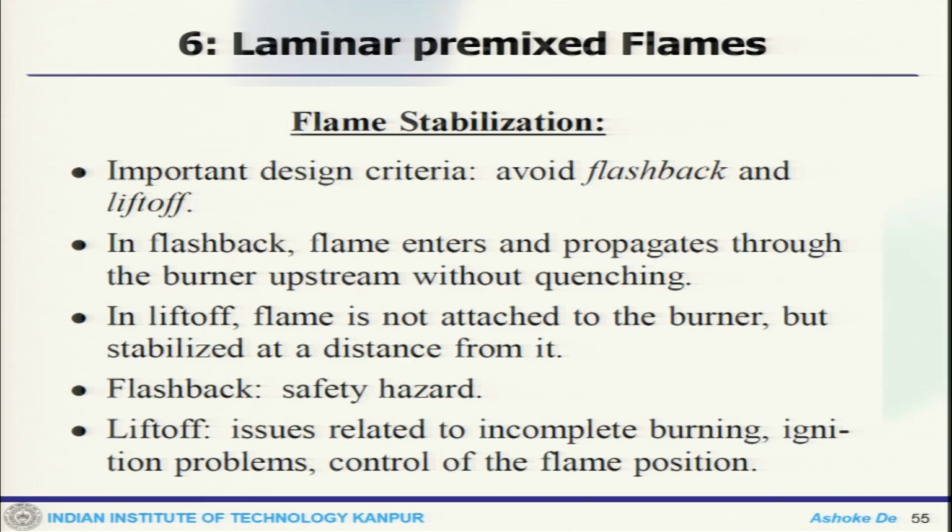Why do we talk about flame stabilization? Because this is very specific and one of the important issues for premixed flame, because we have already seen how premixed flame is susceptible to issues like extinction, flashback, and lift off. It is quite necessary to understand flame stabilization to avoid flashback or lift off, because these affect the design of your reacting system. On one hand, as we have seen earlier, the premixed reaction system has less impact on emission and pollution, but at the same time it is quite challenging to have a controlled combustion in a premixed system.